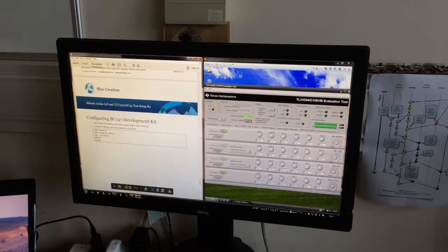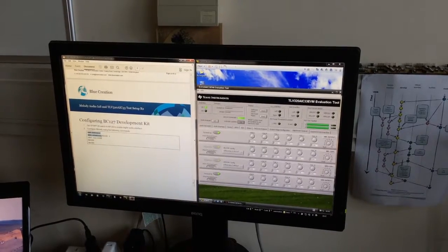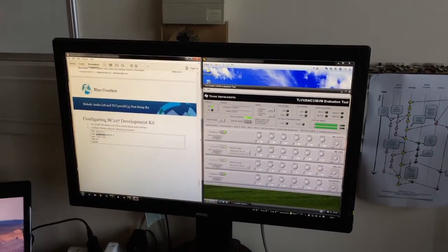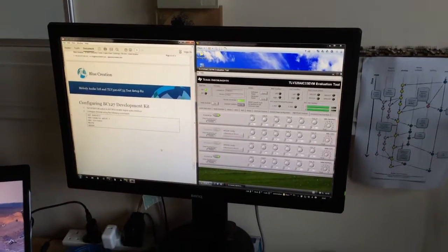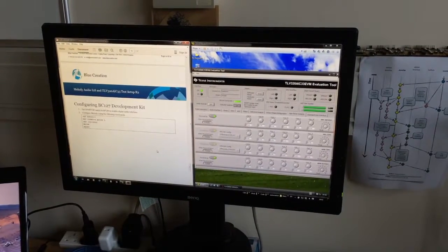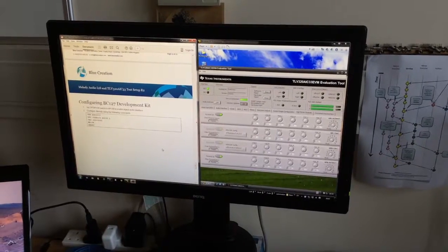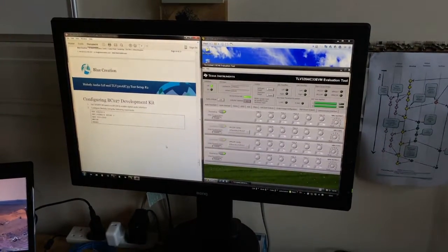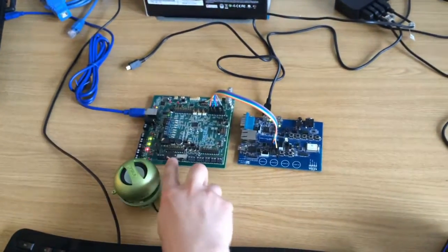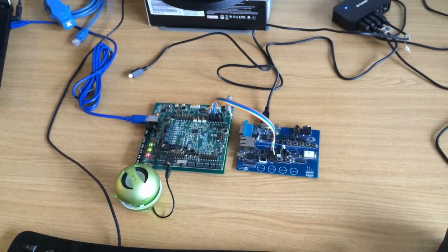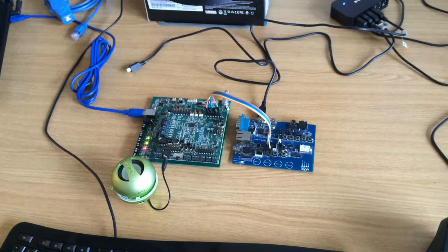So Melody is already configured to use audio equals 3, so I2S master 44 kHz and the default I2S compliant configuration for I2S, and it's paired to my phone. So when I connect my phone to Melody, I should be able to play music, and we should be able to hear it through this wired speaker, which is connected to the iPhone output. I think the gains might be a bit too much.